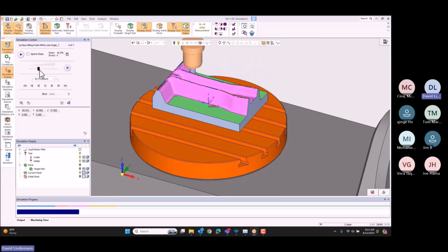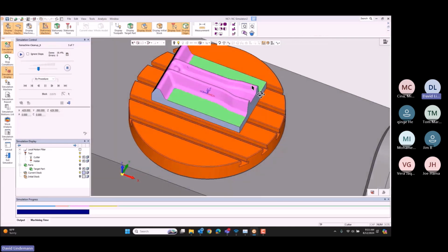This is one of the advantages of course, having that stock statement, is we're not wasting our time cutting air. And on a remachine, that's so important. If it gets into a corner, we want it to finish that corner instead of picking up, moving over, then picking up again and moving over. We call it that sewing machine effect. That's just a waste of time that's valuable. So the toolpath is then optimized or made smarter just so it stays in the areas it needs to stay in.